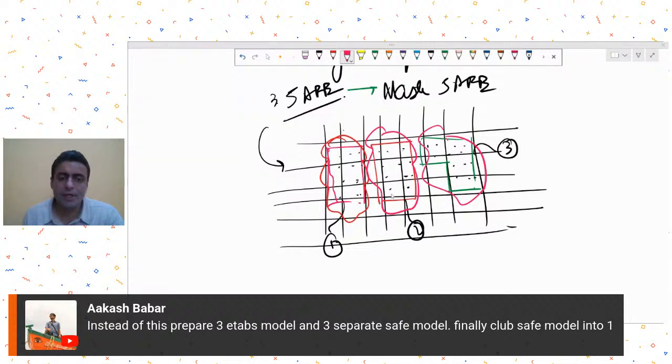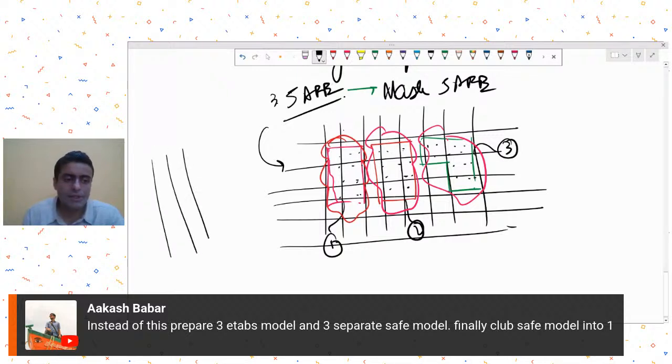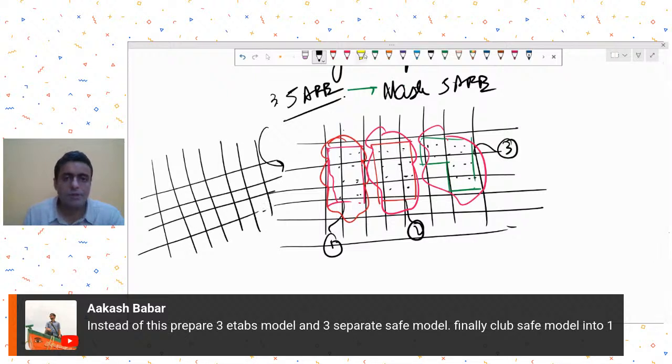That is another way. And I think in that, what you can do is a simple Control C, Control V. I don't know if you have ever tried it or not, but let's say you have a consistent grid already there with you. So you go to a model where only this raft is there. You just copy this and come to this master model, just paste. So automatically it gets pasted at the desired location. Similarly, you go to this individual SAFE model, you just Control C, come to this model, Control V.